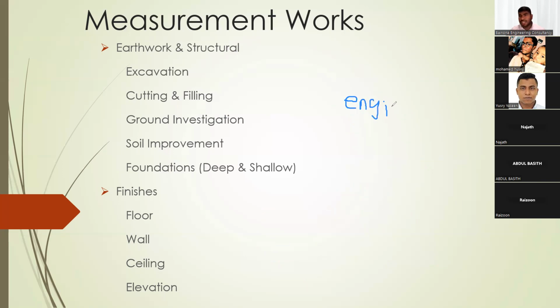So whenever you are writing a letter to the Engineer, if you are a contractor or a subcontractor, don't write with a small e. The small e will go directly to the engineer. You cannot write that as per the engineer's instruction, I will carry out this additional flooring. If I am a professional QS reading this letter from the contractor or the client's point of view, I will ask, who is this engineer to instruct a variation to the contract? He doesn't have the right. The small e engineer doesn't have the right to instruct. The capital E Engineer means the firm. He is the one with the right to instruct variations, because that is mentioned in the Engineer's duties in the FIDIC. If you go to the FIDIC, you will see the Engineer's duties, instructing variations, whatever it is. But I don't want to confuse you right now.